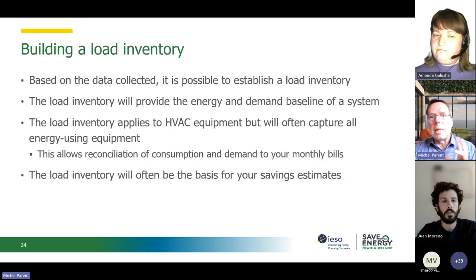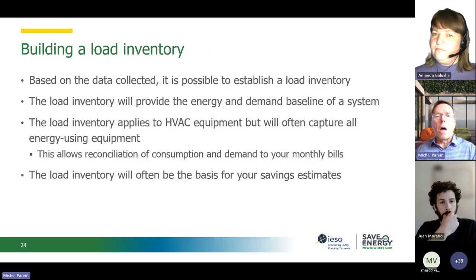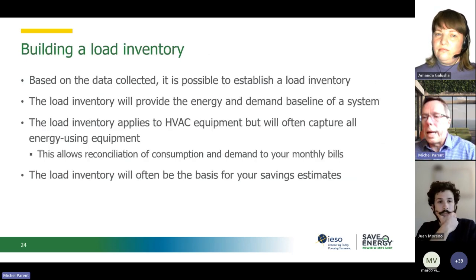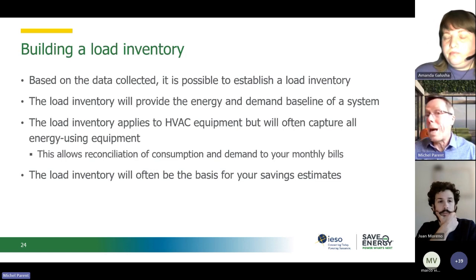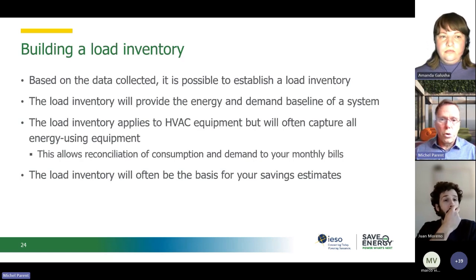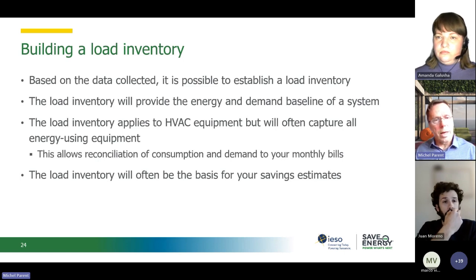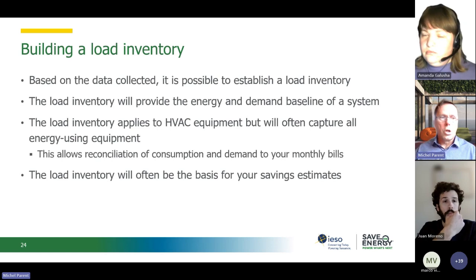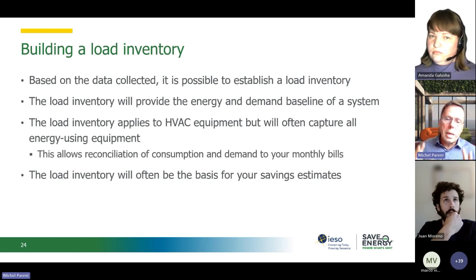The baseline will allow you to know how much energy goes to a given piece of equipment, so your savings estimate can never be higher than that. I've seen many times where vendors come in and promise you the moon. You do your baseline and think, I'm not even using that much here. They're promising me more than I'm using. So you need to be able to establish that baseline.